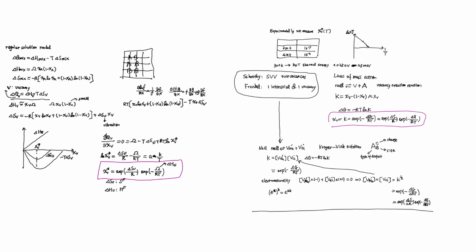So when we have a perfect, pristine iron, all the iron atoms are going to have a certain vibrational frequency. But once you remove some of the iron, you create a vacancy, and the vibrational frequency of the neighboring atoms is going to change. Which means the vibrational entropy is going to change. So without going into the details, approximately we can say we have an entropy change. This is lowercase v, so this is vibration.